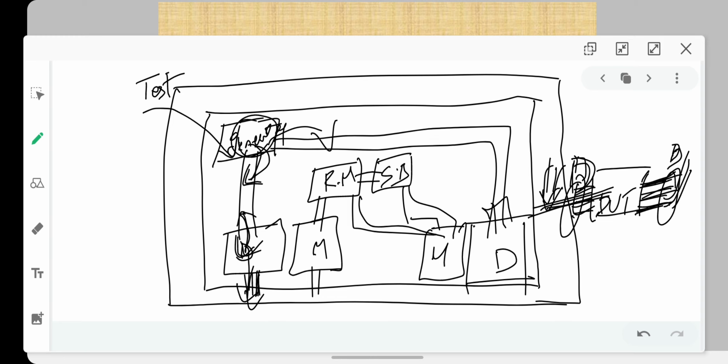In the same way, the data driven from the read side is also put into the mailbox, and from the mailbox your driver gets the data and drives from the read side onto the virtual interface. Once your data is driven into the virtual interface, from the virtual interface itself, both the monitors, on the read side and the write side, are going to monitor the same data that is being driven. Okay, and this driven and monitored data is given to a reference model.